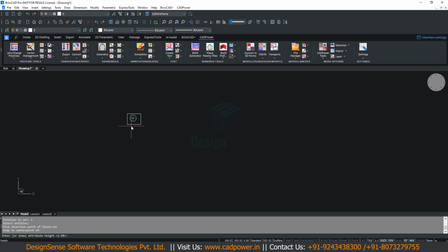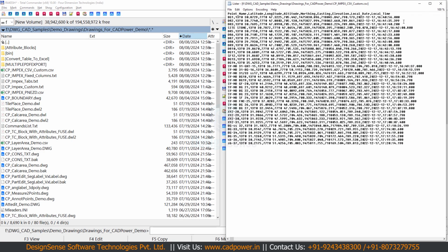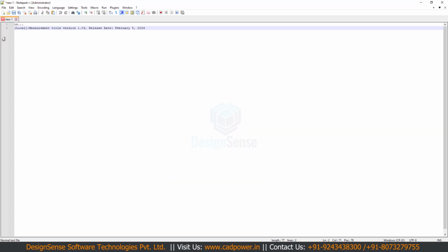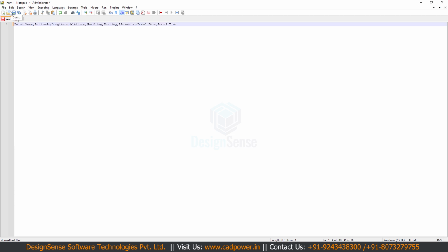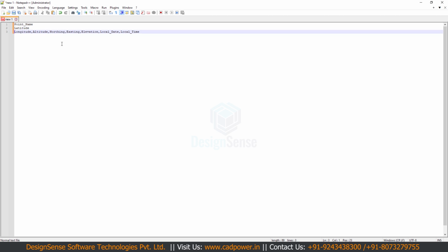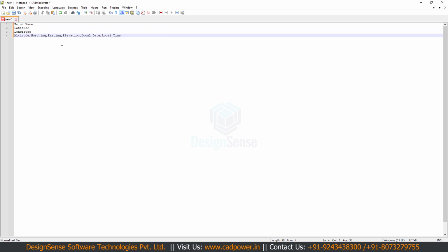Enter or show height. I'm going to specify a small height here, 1.5 approximately. Now it's asking me to enter the attribute tags. You'll have to enter all the attribute tags one by one. To make it easy, I'm going to select all these items here which I want to use as tags, put them all one below the other, and then paste them into my CAD.